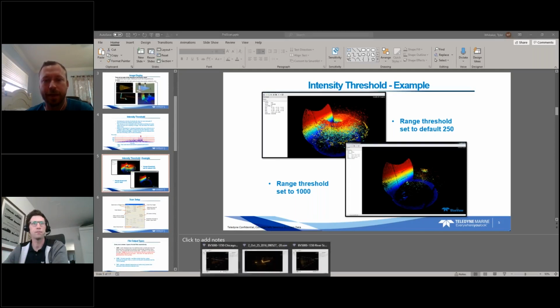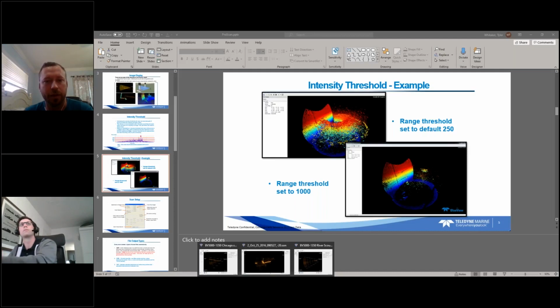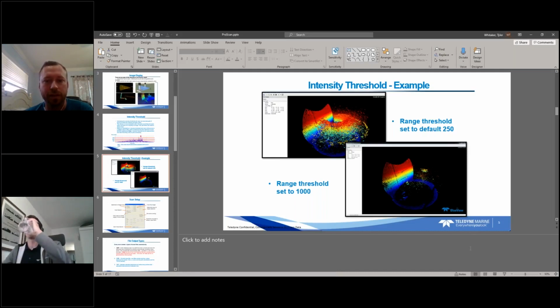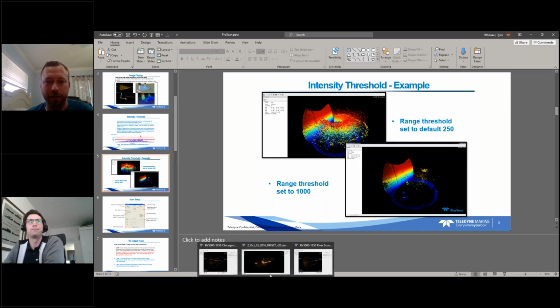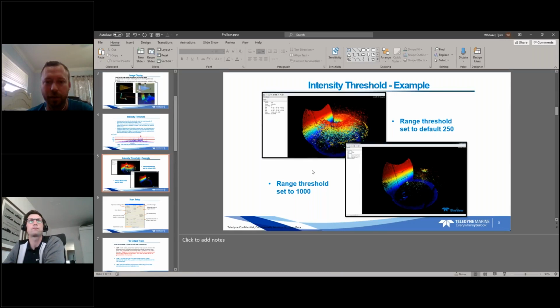And you'll want to be careful though, because especially if you look at that example again, the flat wall itself, if you go too high on your threshold setting, you could start eliminating actual data, not just noise in the foreground. So if you look, can you point out on the left-hand side of that, on the wall, the picture at the bottom? Yeah, here?